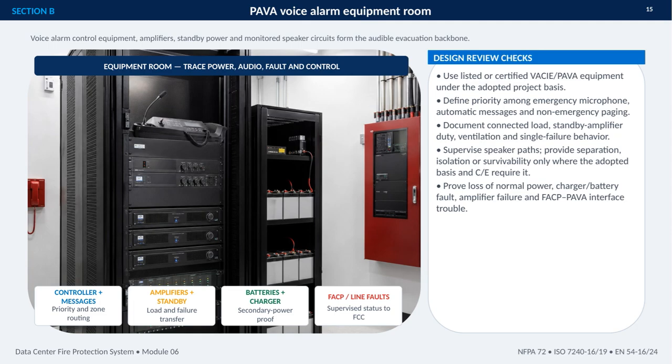I would also verify connected load, standby amplifier capacity, ventilation, and what happens after a single failure. Speaker paths need appropriate supervision, with separation, isolation, or survivability applied where the design basis and code requirements call for it.